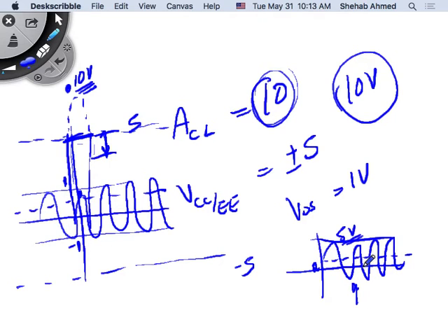So instead of 1 volt, now I can multiply the signal by maybe 3, or 4. So now I have a 4 volt signal peak, and then 1 volt offset. I'm still within my 5 volt range, right? So I can create a circuit with a closed loop gain of 4, have my input signal pass through, be multiplied by 4, so plus minus 4, shifted with an offset voltage of 1. That means I'm at the power supply rail voltage. I still did not lose any content.